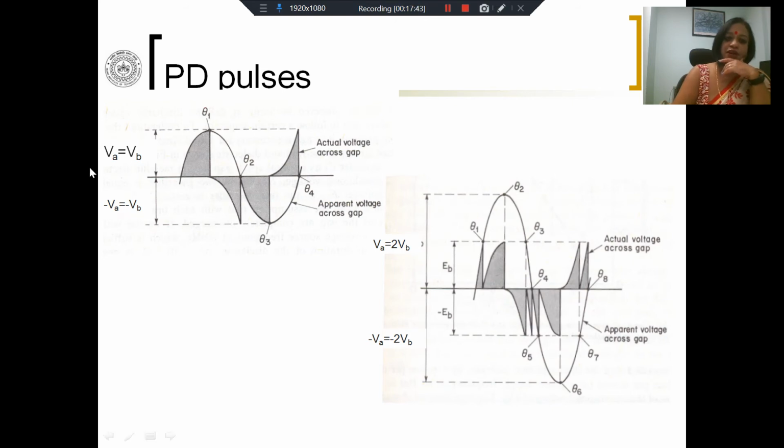So as the voltage across the void begins to fall from VA to 0 because it is following the supply voltage. The supply voltage across the metal electrodes is falling from the peak voltage to 0 voltage. Similarly, the voltage across the void only begins to fall from VA to 0. That is what should happen. However, at the peak instant, the voltage across the void is 0. So if it has to reduce, following the supply graph, what should happen is it should reduce sinusoidally from 0